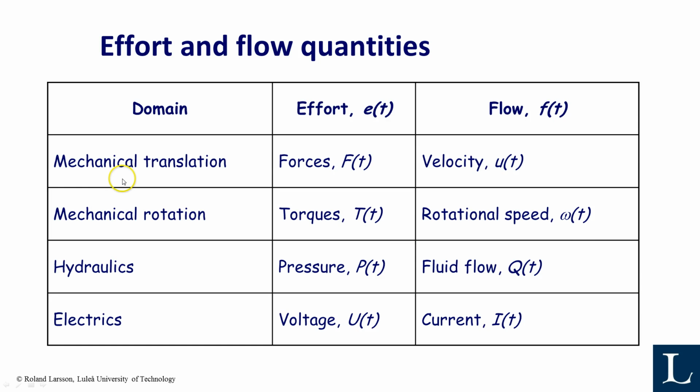If we talk about mechanical translation, then the effort is a force and the flow is a velocity. If we talk about rotation, then the effort is a torque and the flow is a rotational speed. If we talk about hydraulics or fluid mechanics, then the effort is a pressure and the flow is the fluid flow. And in electrics, the voltage is the effort and the current is the flow.